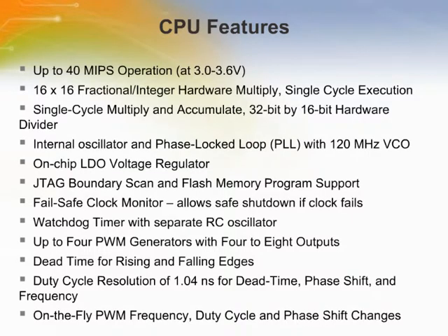This device contains extensive digital signal processor functionality with a high-performance 16-bit microcontroller architecture. dsPIC33F switch mode power supplies devices feature several advanced peripherals, such as a high-resolution pulse width modulation, a high-speed analog-to-digital converter of up to 4 megasamples per second, 10-bit analog-to-digital converter, and a high-speed analog comparator module.